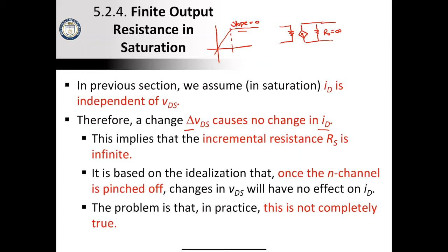And also, if I were to really quickly draw the MOSFET, and we have the channel. The channel starts off as a rectangle. It gets more and more trapezoidal. Then it eventually becomes a triangle. We have assumed so far that once it becomes a triangle, this point never starts to move to the left, which is called pinch-off.